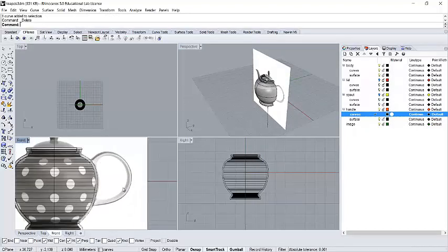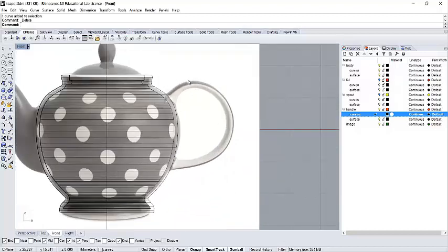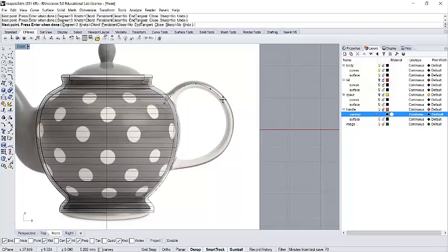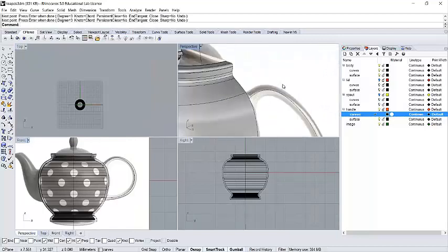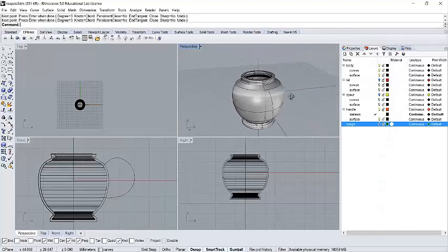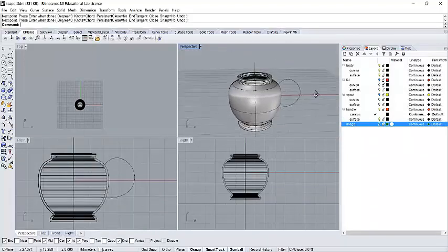So if I was to try and draw this handle, it would make sense to start in a side view, and I'm going to do this overarching curve using a spline, and I'm actually going to go up the middle of it. As mentioned before, the fewer points you can click the better. I'm going to go into the body on both ends, because that's going to come in useful later. Okay, so you see that's drawn there. I can turn off image now. So we've got the start of this handle.